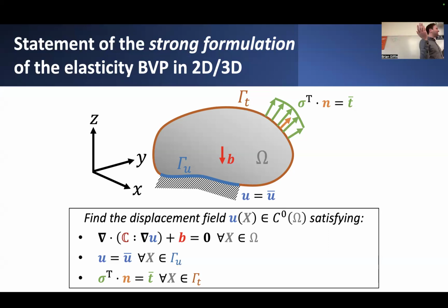No, so that's a problem, right? It basically means that I have additional differentiability requirements on the solution that I can obtain. And in fact, they're somewhat unphysical in the sense that they impose these kind of onerous conditions on effectively what are continuity requirements on material properties, and also continuity requirements on the derivative of the displacement field or the displacement gradient. So both of those things make it difficult. The fact that we're trying to solve an infinite dimensional problem is one issue. The other issue is these kind of differentiability issues.